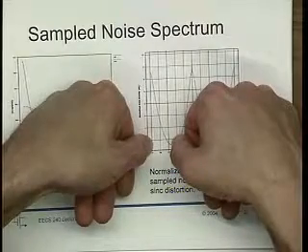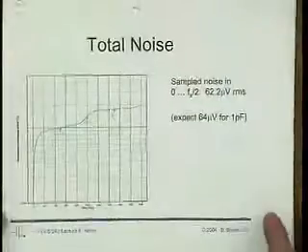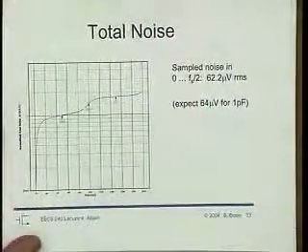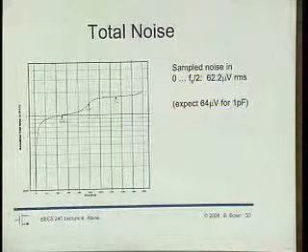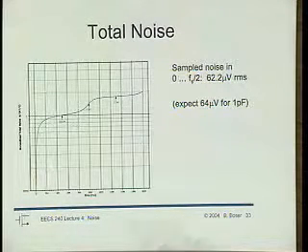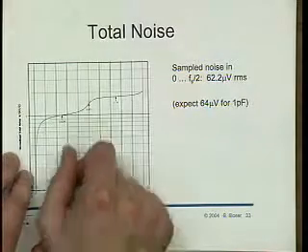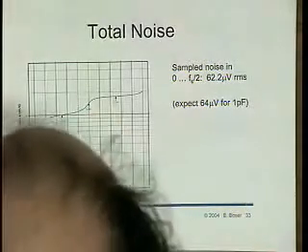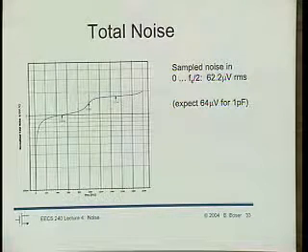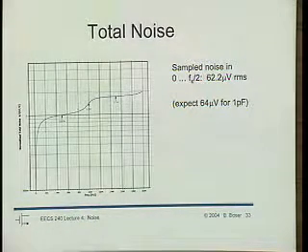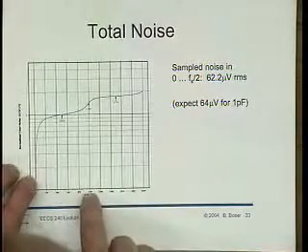So I did this experiment with a 1 picofarad capacitor, and then I integrated. And I wanted to just know, well, how accurate is SPICE in predicting that? So here is the result. Instead of plotting just the integral, I normalized the integral with kT on C, where C was the 1 picofarad capacitor, right? And so this at Fs over 2 should be just 1, and lo and behold, it's 0.4% larger, and so by the argument that we used earlier, I'm happy with that, right? Sort of.